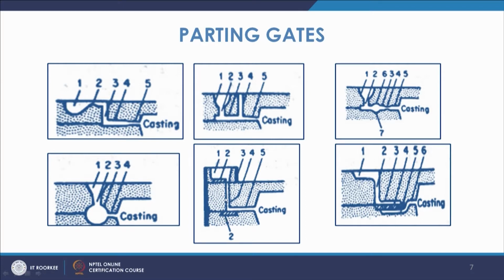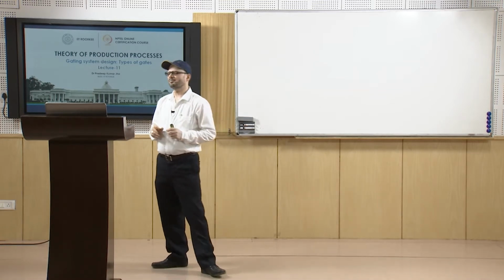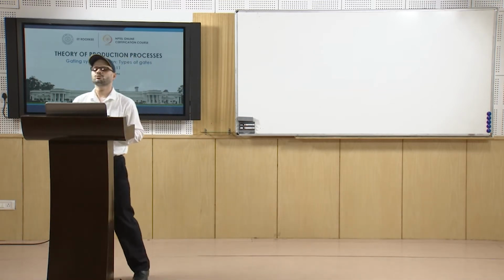So, this way, and then you have other elements like the sprue and the pouring basin, ultimately coming to the casting. Now, in this case the metal gets filtered through it; a strainer core is there, and the metal will come through the strainer core first and then enter into the casting. So, you will have the provision of filtering the liquid metal before it enters the cavity.